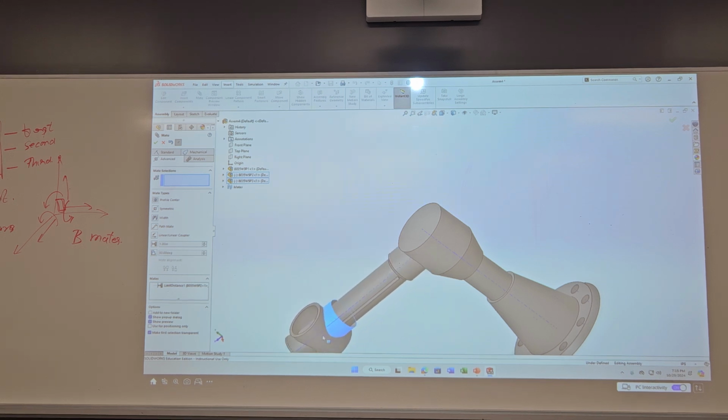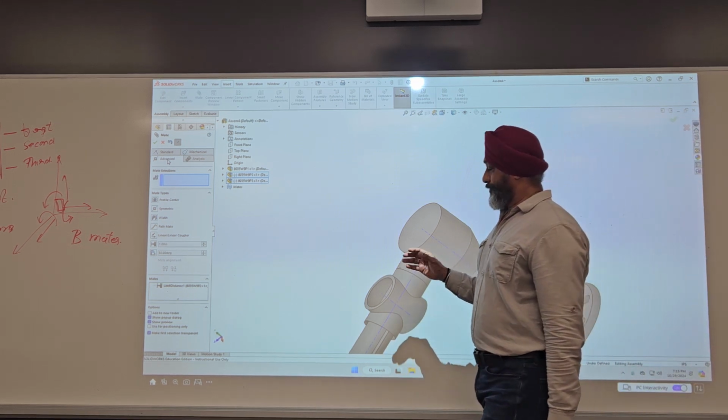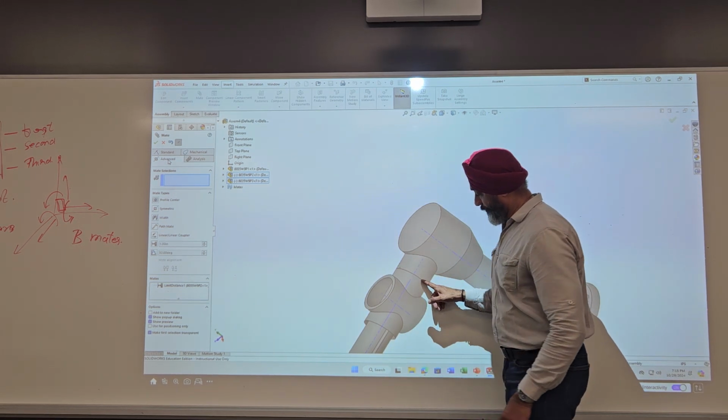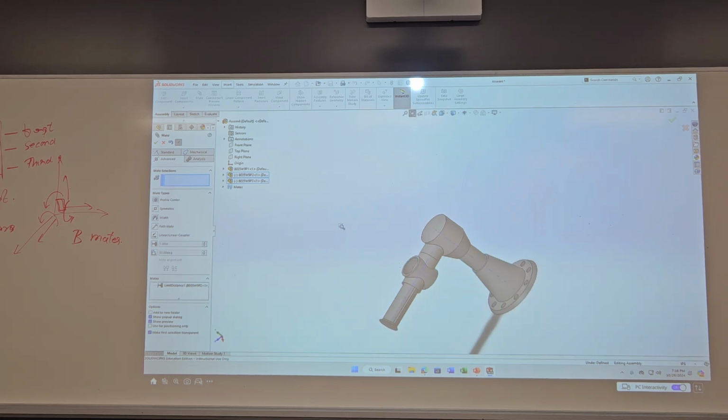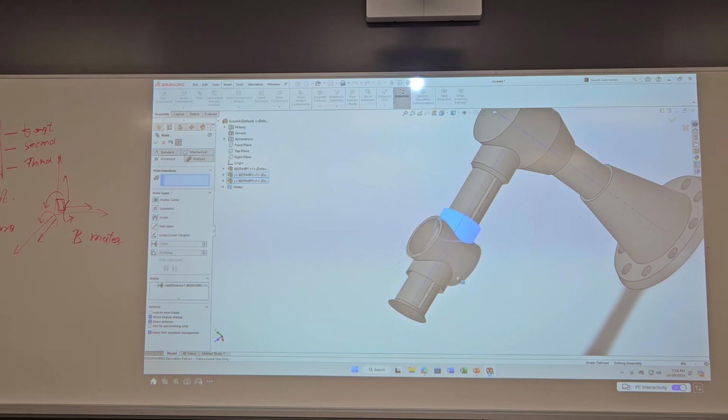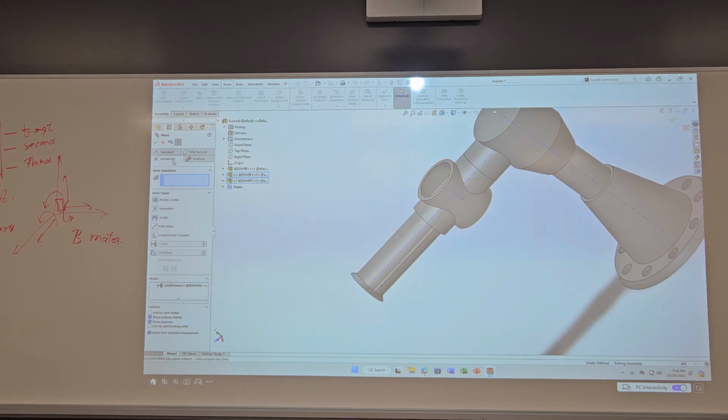Okay, so if I made the minimum distance 0, and these are under advanced. This won't be part of our course, but I still want you to look at it and see how to use it. So we want to control this movement between this face and this face. In this case we can use advanced with the linear distance, minimum 0 and maximum, I don't know, let's make it 2.